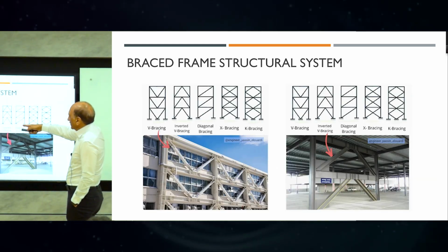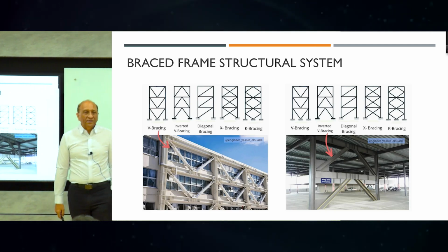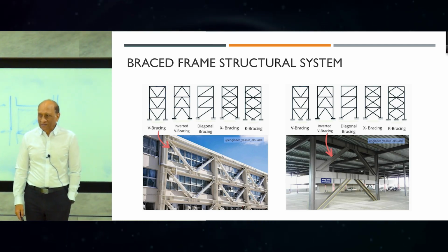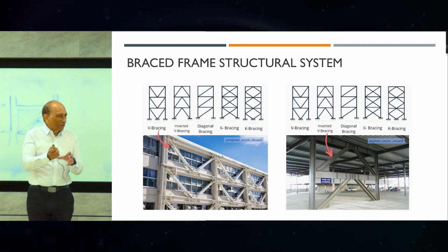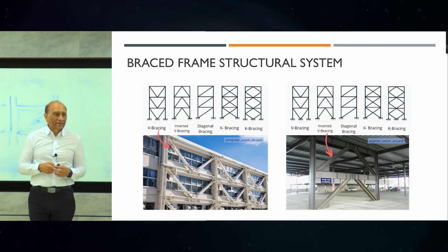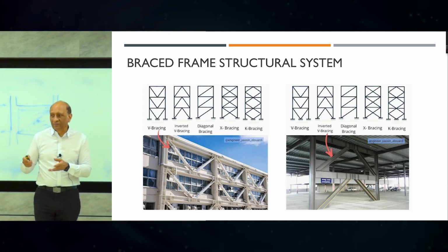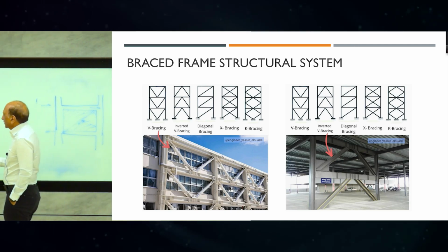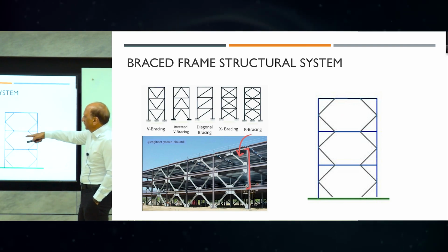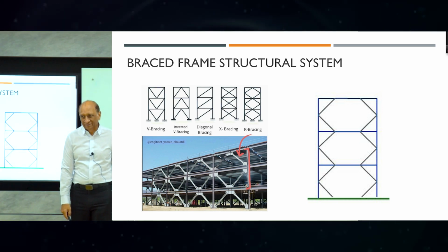So you can have different kinds of bracings, mostly for steel. You can see over there shapes, all kinds of bracings are used. But bracing is quite helpful for wind and steel building. Concrete, very hard to make a brace. Not easy to make an inclined column, or jointing is so hard, the reinforcement is all messed up. So normally in concrete building, very difficult to use braces, unless it's a steel brace that you put inside the concrete frame building. You can also do bracing like this, K bracing, knee bracing, V bracing, inverted V bracing, but you can see mostly low-rise building, mostly steel, but they are very effective.